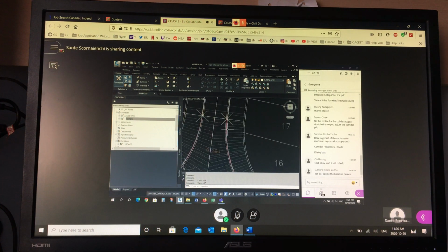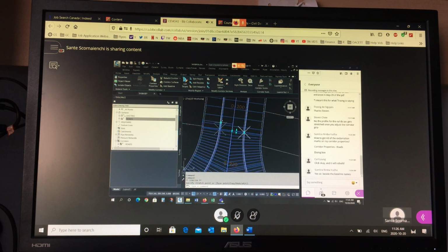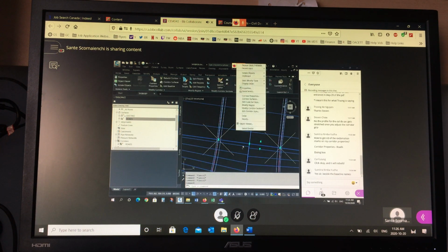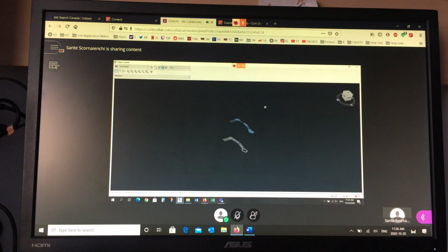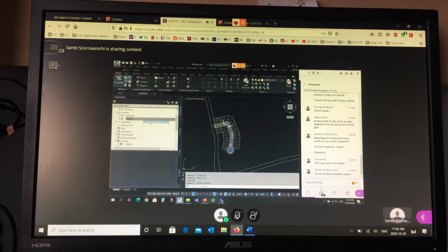I'm going to click on here, grab the grip in the gutter, and snap it to the beginning of the profile design range. Grab this grip and snap it to the profile, which is this point. That gets rid of the spikes in the data, and that'll get rid of the spikes on the surface. So let's bring your surface back to life.